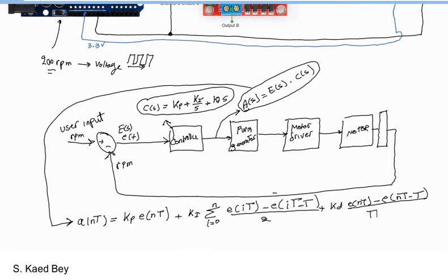Whereas here now, we will implement the controller. Here we have to use the encoder information and subtract it from the user input to obtain the error. Now we always need to maintain the error at 0 as much as possible with the help of the controller. Now implementing this difference equation in Arduino Uno will allow us always to output a PWM that is suitable to control the motor and bring the output RPM of the motor equal to the user input.